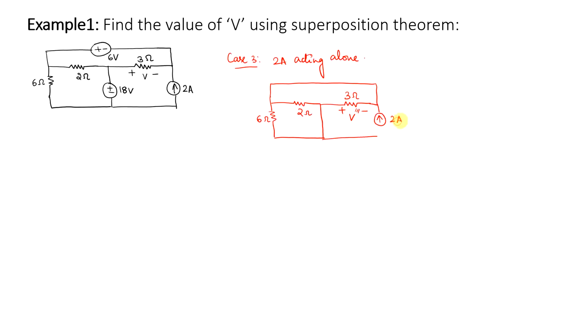So you have in total 3 meshes. So apply the equations for the mesh currents I1, I2 and I3. So write the equations. From mesh 3, you can see this current source is exclusively to this mesh. So I can write the current I3 to be equal to minus 2 amps because the direction of the current source is opposite to the direction of the mesh current.